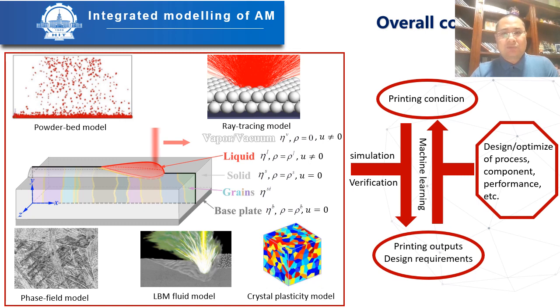To address this challenge, modeling and simulation have emerged as valuable tools. We have developed an integrated platform for powder bed-based additive manufacturing. Our platform incorporates the phase field method for simulating phase transformation and defect evolution, the lattice Boltzmann method for multiphysics dynamics, and the crystal plasticity method for stress-strain responses. Additionally, we've created models for powder bed generation and a ray tracing method to handle powder bed interactions and laser material